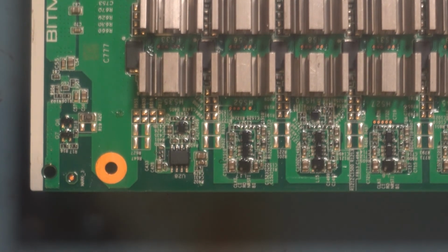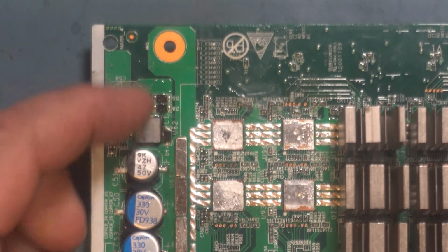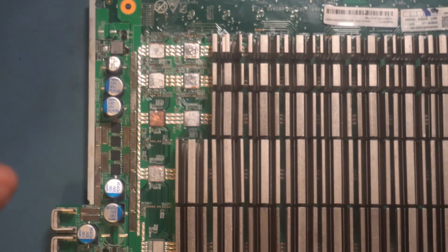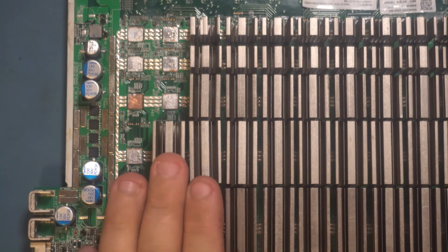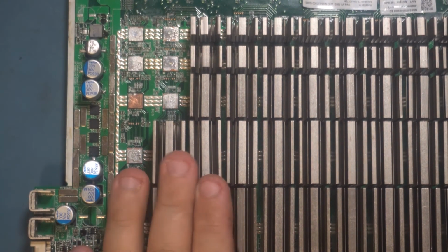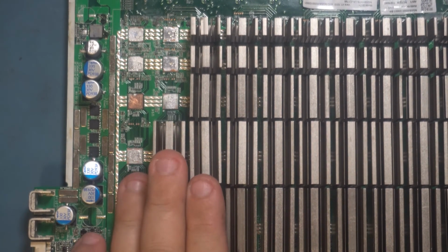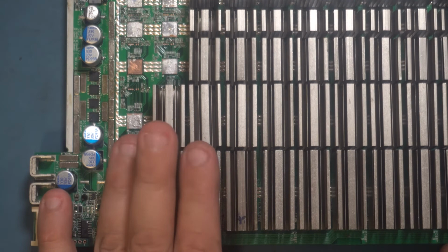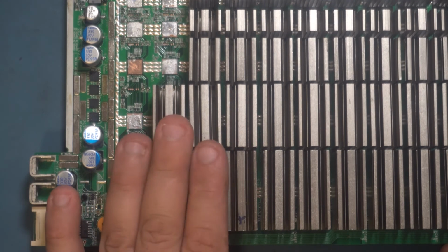So when you don't have a boost circuit like this board doesn't have right now, it's missing the chip, it won't change anything except the 1.8 and the 0.8 on the domains that use that higher voltage to regulate it down to generate those voltages. So in the case of this S17 Plus, I believe it's the last three domains.